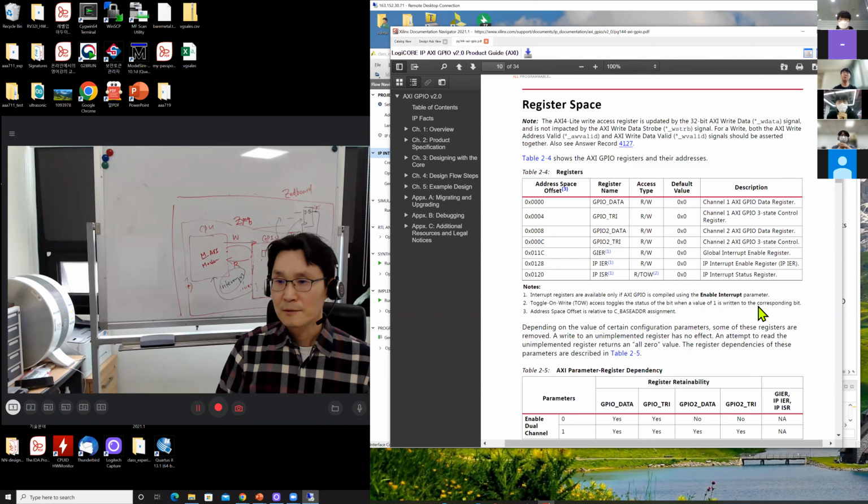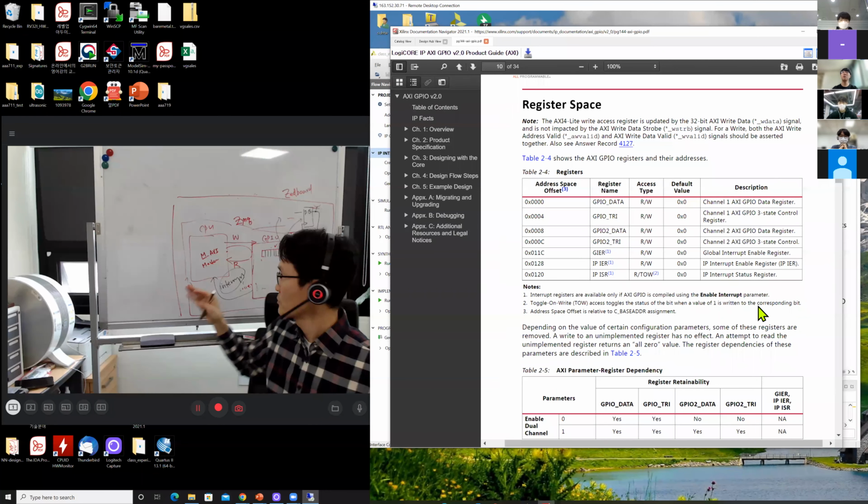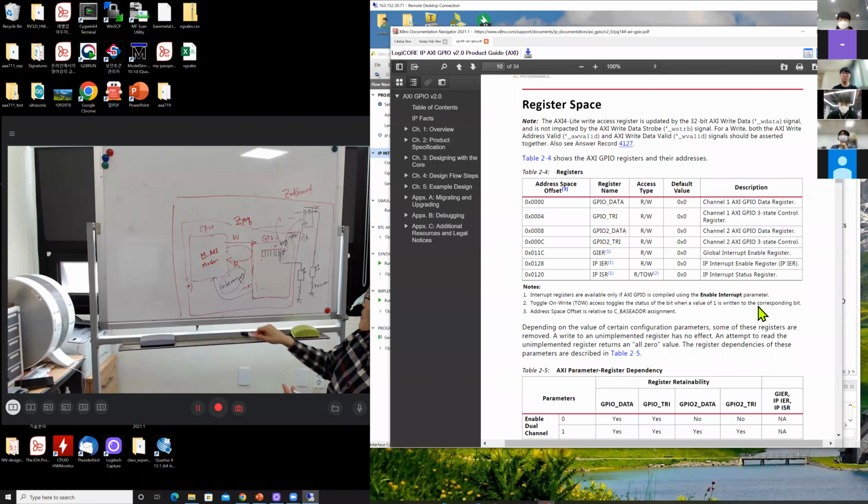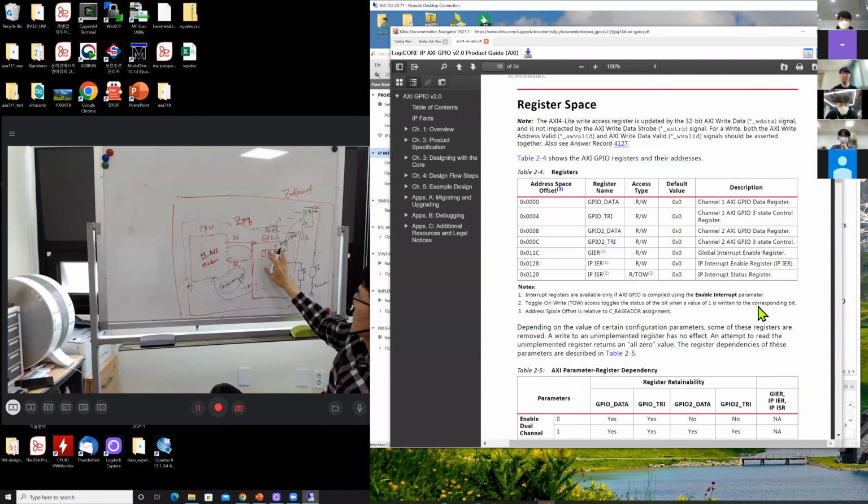So think about your network interface card, NIC. You want to send a request to CNN.com to see the front page. You are sending a request packet, and it goes through the Ethernet connection to the CNN server. Then the response packet comes in and is stored in the internal buffer of this device. That is an event: response packet arrived. CPU, you have to do something, I have a response packet. So interrupt, something like that.